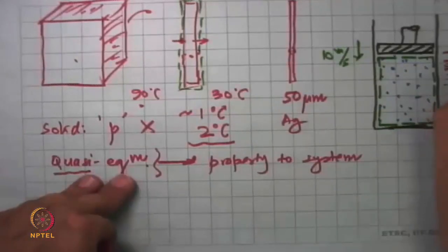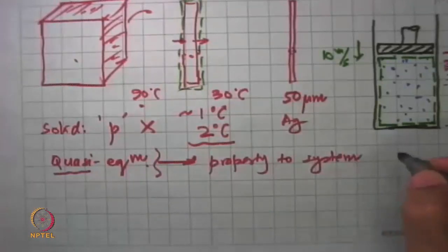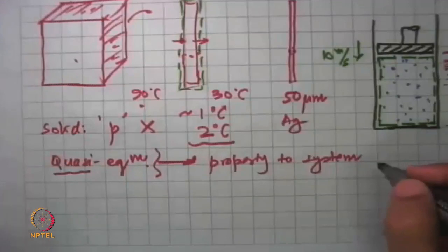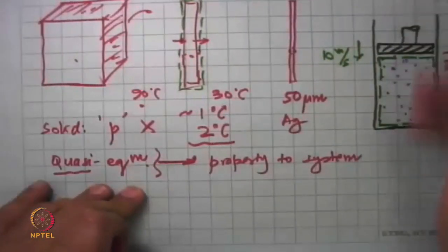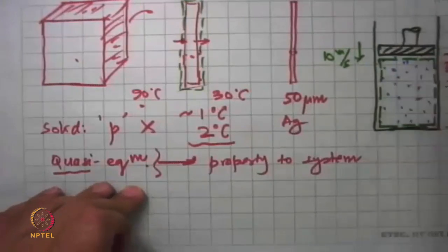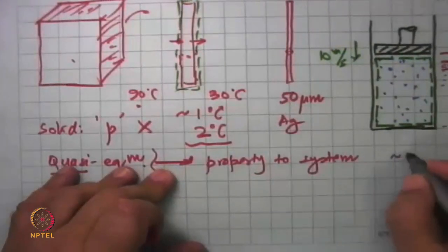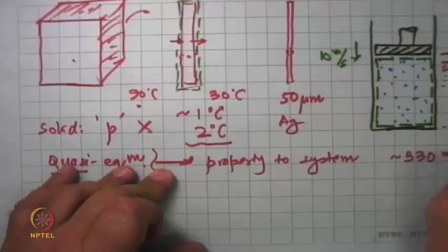The speed with which this wave travels is the local speed of sound. And that is the case with not just gases, but also with liquids and solids. It's the same formula that comes from physics. In air, at about ambient conditions, it depends only on the temperature, not so much on the pressure. At ambient conditions, the speed of sound is of the order of 330 meters per second.